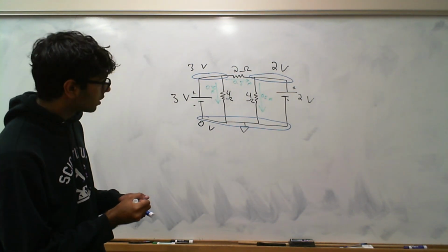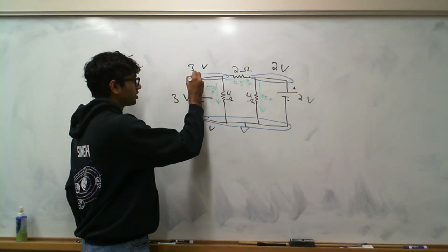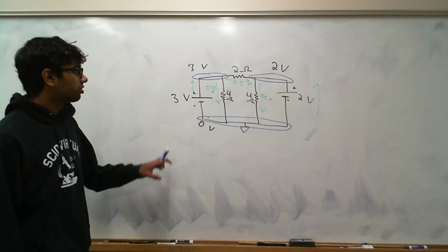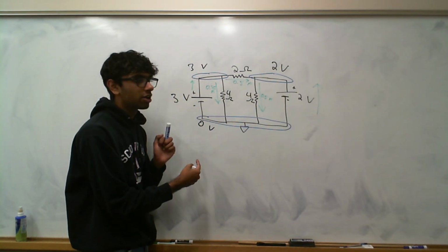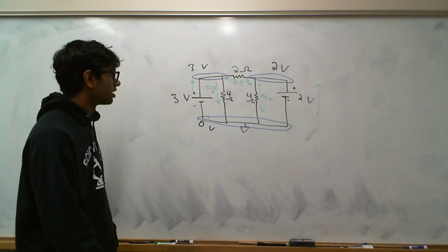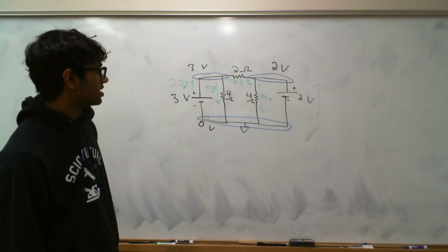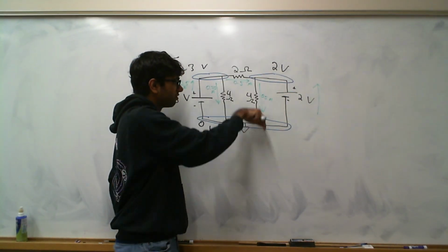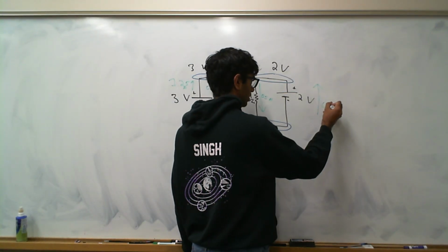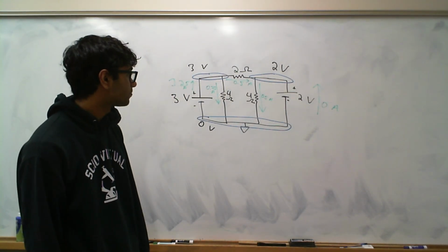Okay? So, there's only one other current to consider for both those junctions. How much current is here, and how much current is here. Because remember, there's only one other place where current can go in or out to this node, and same for that node. So there's 0.75, 0.5 leaving there. So actually there's 1.25 amps flowing into there. There's 0.5 going in, 0.5 going out. So actually 0 current flows here. That's pretty weird. It's like that battery doesn't even exist.